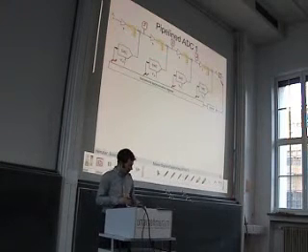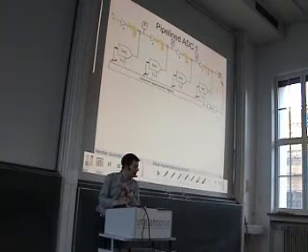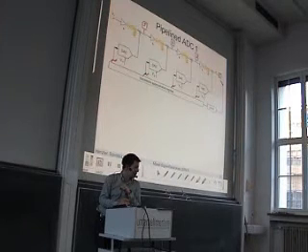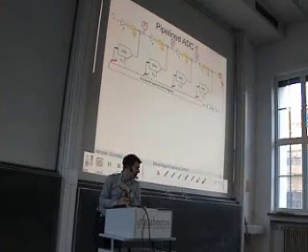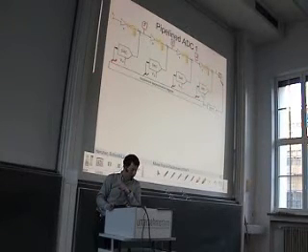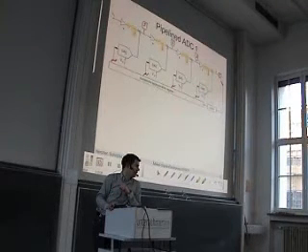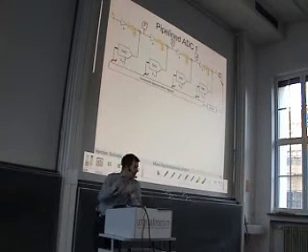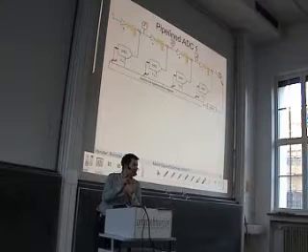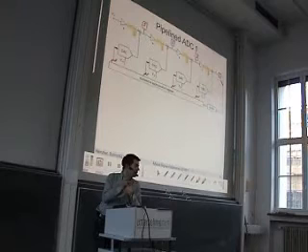So somehow we increase the effort because we need these comparators in each stage and we need the additional sampling elements. But after we have this, we can enable this pipelining, which means what at the end? That we do not need n iteration cycles, but that we can latch in a new input sample in each iteration cycle.